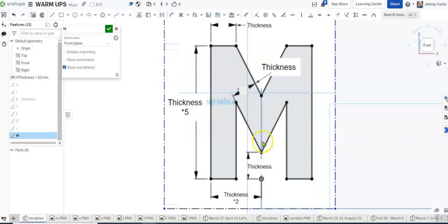To do so, we can see that there is a line going down the center, and the two halves of the shape are symmetric and equal to each other. A uniform thickness identified here. So think about design intent. This is a letter M, like you'd use for a sign of some form. So you would have a uniform stroke width, which is called thickness. So that tells us a lot about the design.